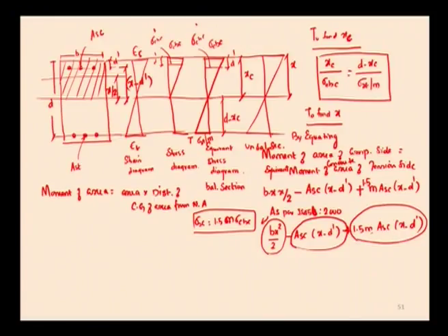So, here for compression bars where the compressive resistance of the concrete is taken into account, the stress shall be the calculated stress multiplied by 1.5 times the modular ratio. Here the stress is multiplied by 1.5 times the modular ratio, then this area should also be multiplied by 1.5. So, here which is equal to equivalent moment of concrete area of the tension steel.